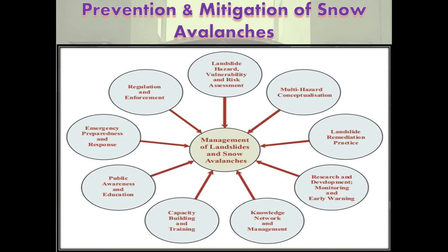Engineering structures for the control of snow avalanches are of the following four types. First is supporting structures in the starting zone, built on the upper part of the avalanche path to prevent avalanches from initiating, or to retard movement before it gains momentum. Massive earth or stone walls and terraces, rigid structures made from wood, steel, aluminum, pre-stressed concrete, or a combination of these materials, and flexible supporting structures called snow nets, constructed of steel cables or nylon straps and held up by steel poles,